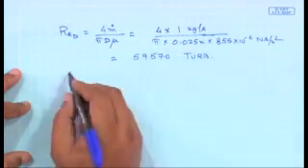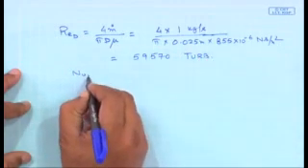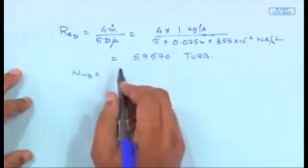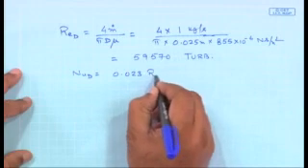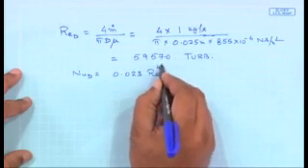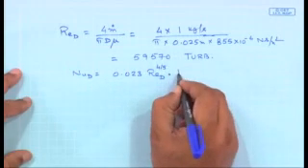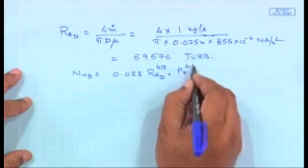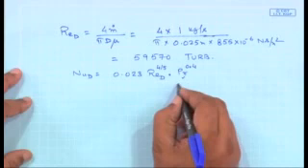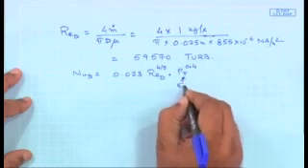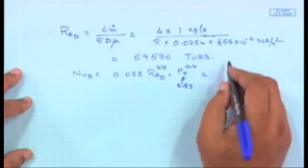So, if it is a turbulent flow, then I can simply use the Dittus-Boelter equation for finding out the Nusselt number, which is 0.023, Reynolds number based on diameter to the power 4 by 5 times Prandtl number to the power 0.4, and this Prandtl number is provided as equal to 5.83 in the statement of the problem.